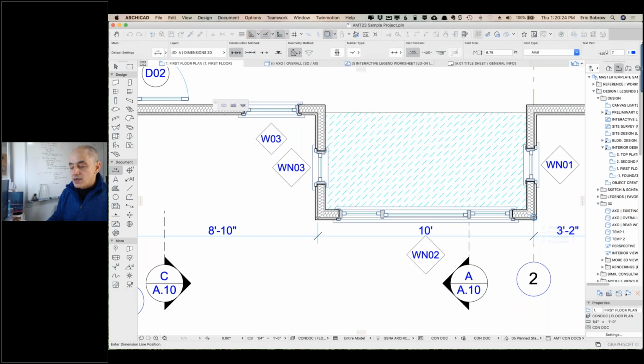So if you did want to get it a specific distance away, I might put it on that location. Well, actually, what we need to do is put it somewhere parallel to that, like on that line. Oh no, okay, so we have a little bit of an issue in the sense that when I click on a line, like an edge of a wall, it's actually putting in references to both sides. Let me just unclick these by clicking them again. So we get rid of those.